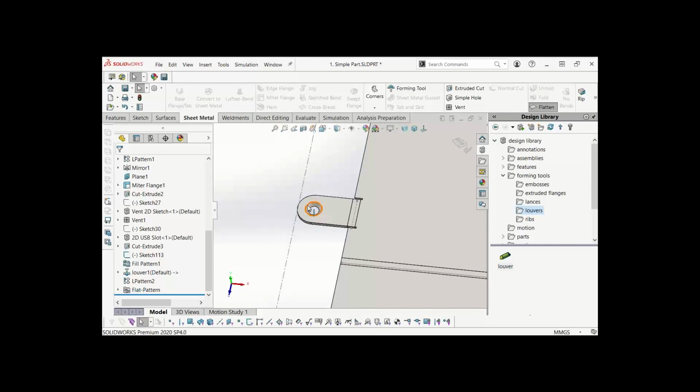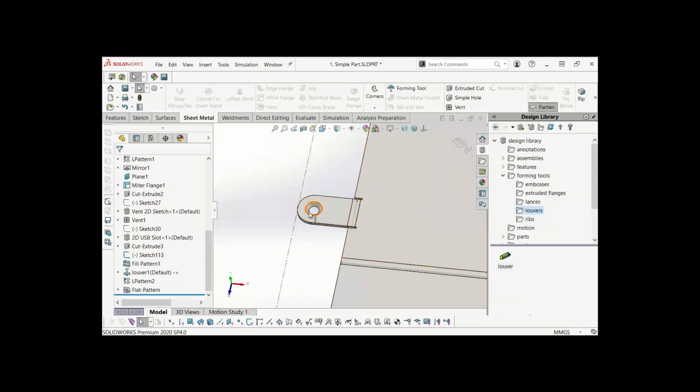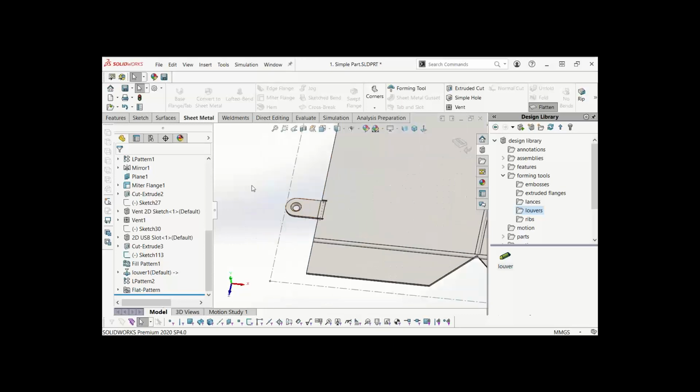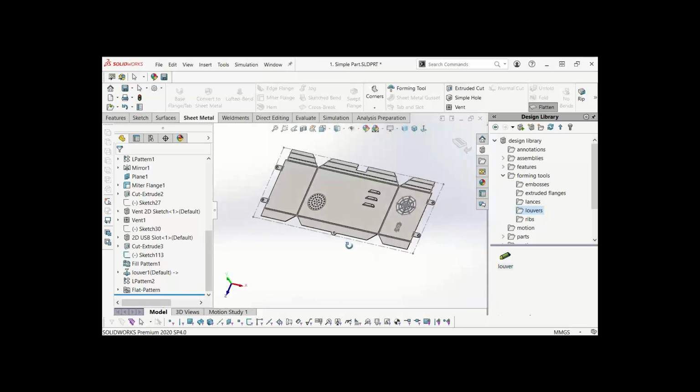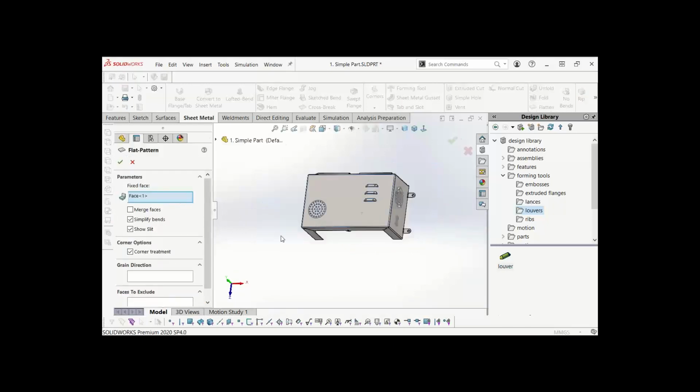For example, this countersink is going to be done after completing the folding operation. After that, they're going to do this operation on the shop floor. So I do not require this phase, right? That's one thing. Okay, so in this, I have some additional options here with flat pattern where I can edit features.